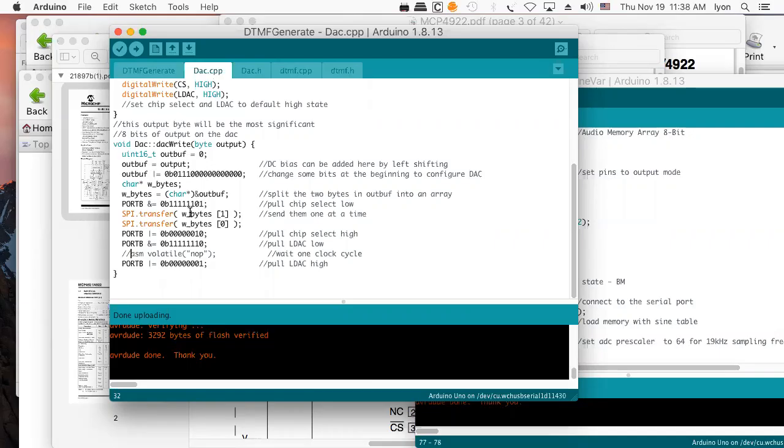So that seems to be working, right? But that NOP, what is that doing? It's giving you a small delay, no operation, where the CPU sits idle as you flip this bit from 0 to 1. And that is all it does. It could be useful for reading the output, right? No operation, doesn't read anything. It doesn't write anything. It just sits there and cycles a little bit of CPU time.